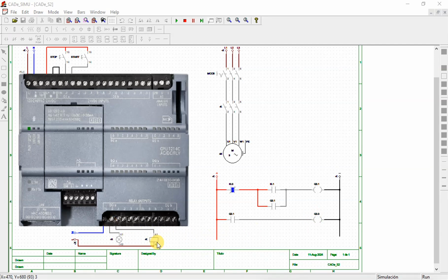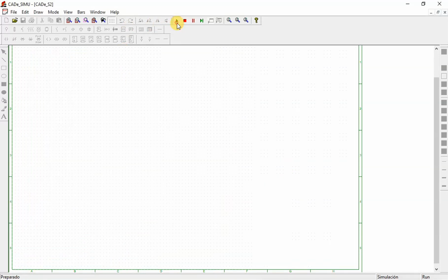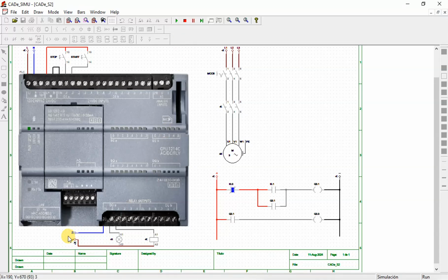The coil is connected at Q 0.1, which is this one, and our stop is connected at pin I 0.0, which is around here, and the start push button is connected at pin I 0.1, which is here. So when we do a simulation here, remember this power supply here and this one, I just made them different because of space. I didn't want to overlap cables, but if you are wiring in your panel, you use the same power supply, no problem.